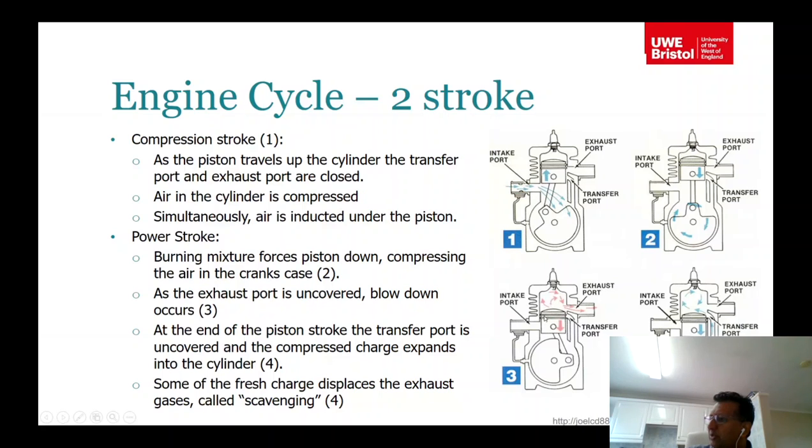So the intake port is closed when the cylinder is at this point, and then you know that exhaust gases will be expelled from here. When the cylinder goes up to this level, this port will be open, and the exhaust port will be closed, and air is coming into here. And then there is another transfer port as well, which will allow some of the exhaust gases to come in here.